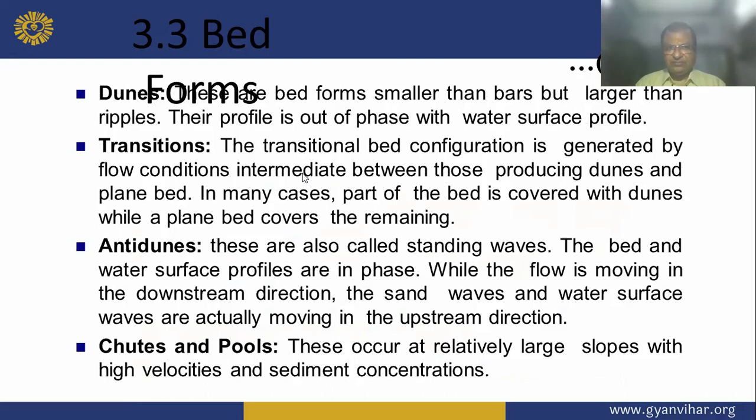Now dunes. What are dunes? Actually, in the riverbed, many small steps have been developed, and these are called dunes. Dune bed forms are smaller than bars but larger than ripples. They are out of phase with the water surface profile.